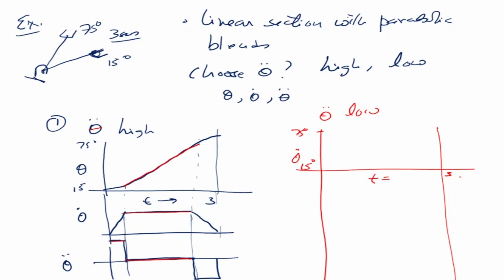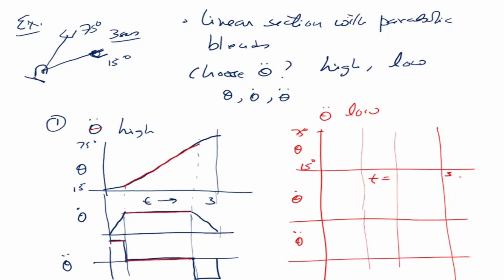So we'll see that what basically happens is when acceleration is lower, okay, this is velocity, position, and acceleration. So this is theta dot, and theta double dot. Okay, so basically what we are seeing is that the time of blend has gone up now. Your time of blend has gone up like this, then it becomes a straight line, it comes down like this. Okay, so correspondingly in the velocity graph, the velocity has gone up like this, it has remained constant and come down like this. Okay, this region has become smaller.